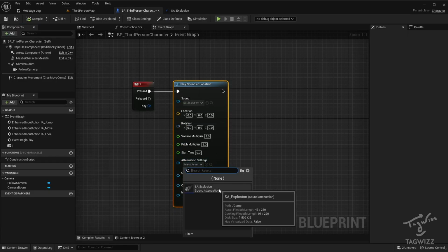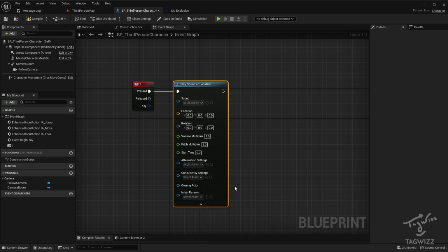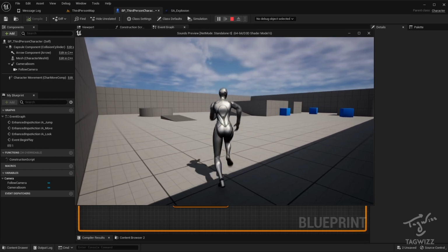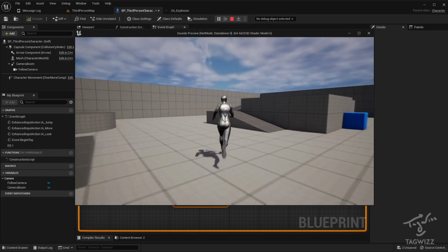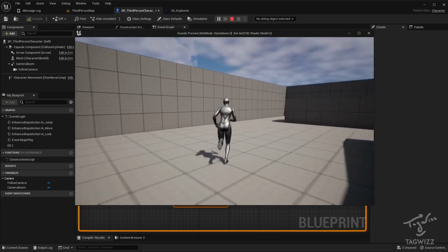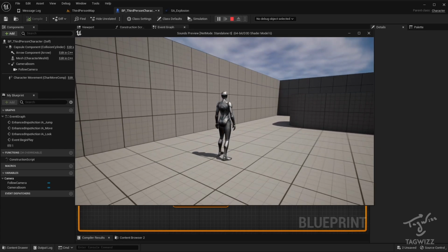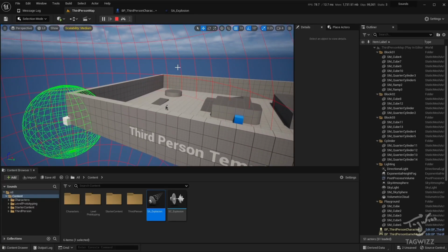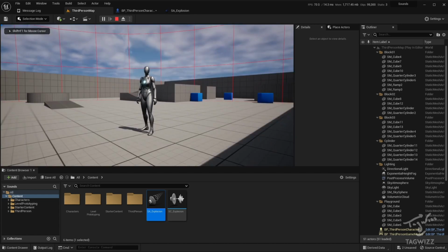Without modifying the other options, we save this asset and now configure it to play the sound from the block, Play Sound at Location. By clicking play, we can notice some new aspects. First, when we are close to the source sound, the vector 0, 0, 0, the sound is at its maximum volume. As we move away, this volume begins to decrease until it reaches the maximum radius configured previously, 2500 units.